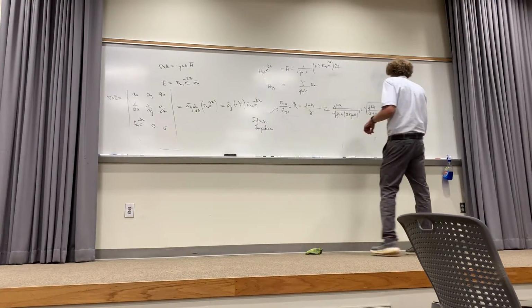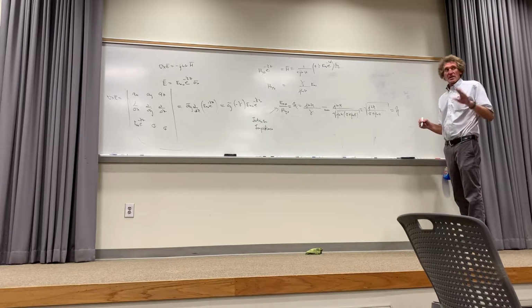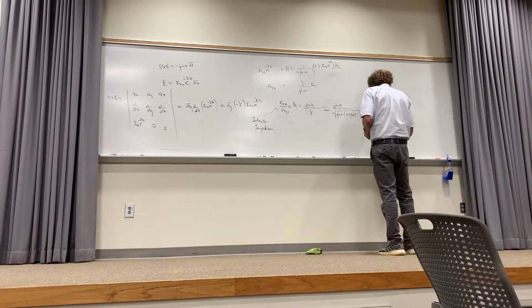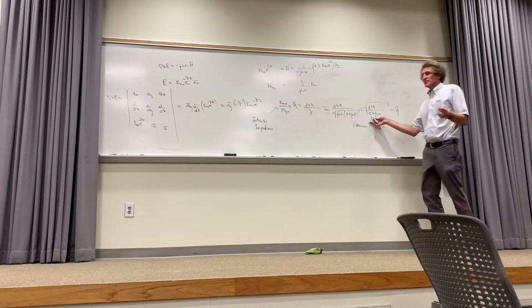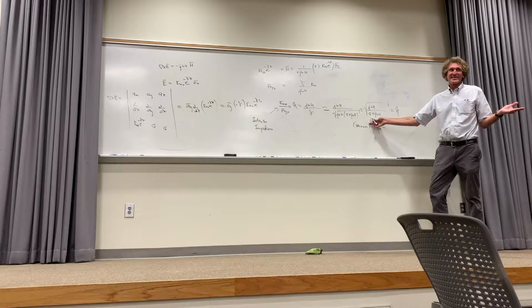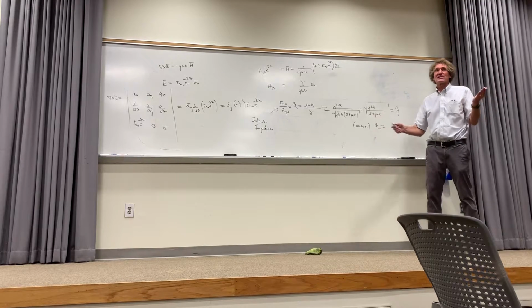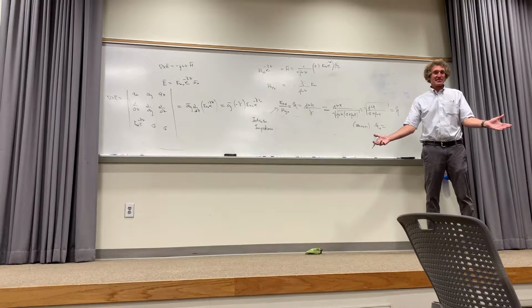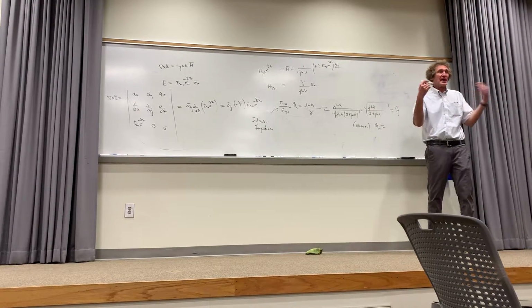Now, what I'm about to tell you is important. That's j omega mu over sigma plus j omega epsilon. So let's take a look at this for free space. Free space means a vacuum. So what is the value of eta in a vacuum or free space? Well, in a vacuum, what's sigma? I mean, just tell me what sigma is. The conductivity. What's the conductivity of a vacuum? It's 0, right? There's nothing that conducts. A vacuum is void of charge. You can't have any conduction at all.